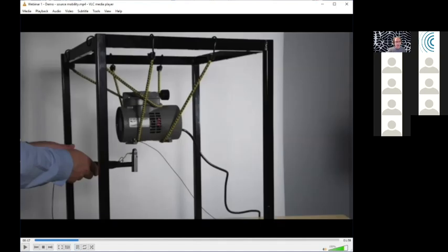And here you can sort of just see through the grill. So we're aware that we have a very complex inside, that the housing hides all of these internal components. But what we want to do is say, okay, we have a very complex machine here, but actually when you're considering structural dynamics at low frequencies, it's often possible to represent fairly complex structures by a combination of a few masses, springs, and dampers.